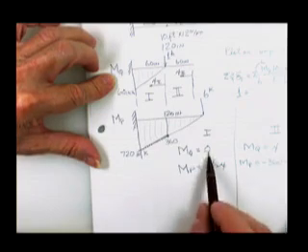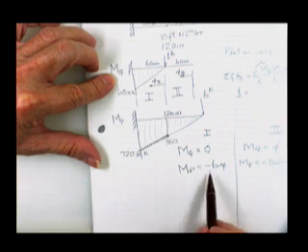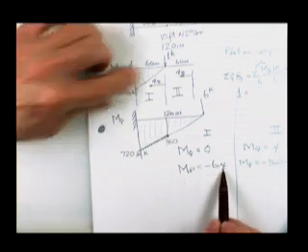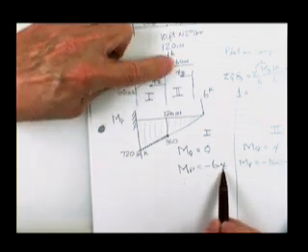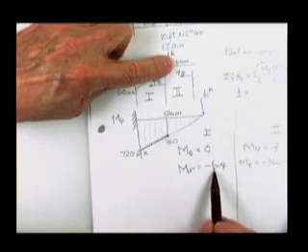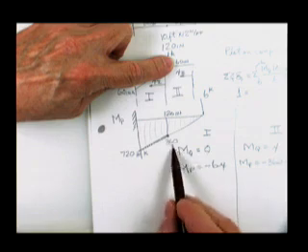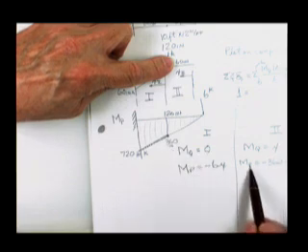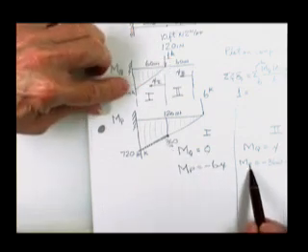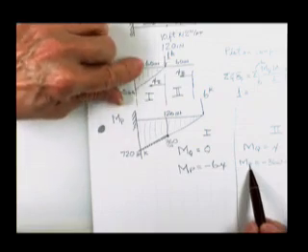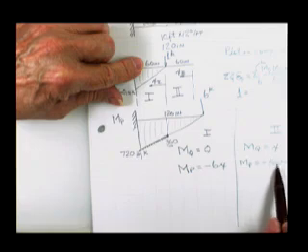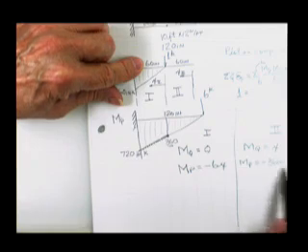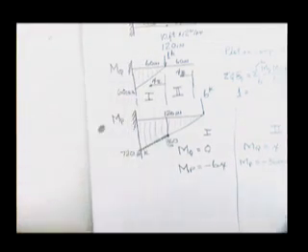Check the boundaries. M sub p is equal to minus 6x when x is equal to 60. You should have 360. That's okay. When x is equal to 60, you should have minus 360 minus another 360. That's minus 720. If it fits those end conditions, you're probably okay.